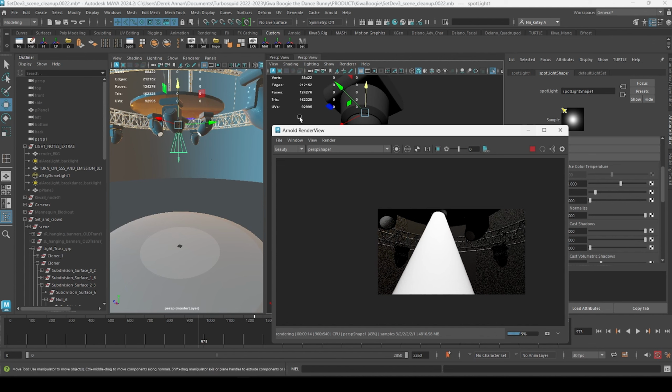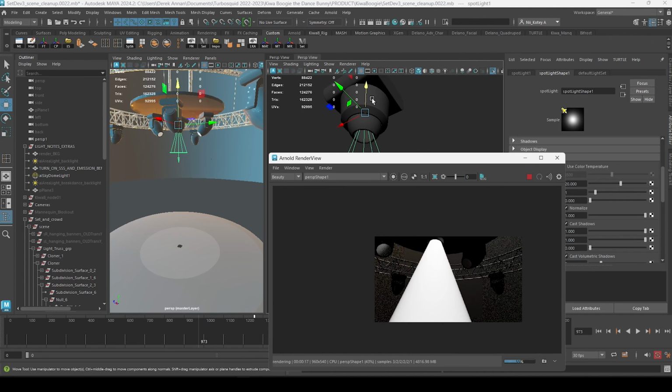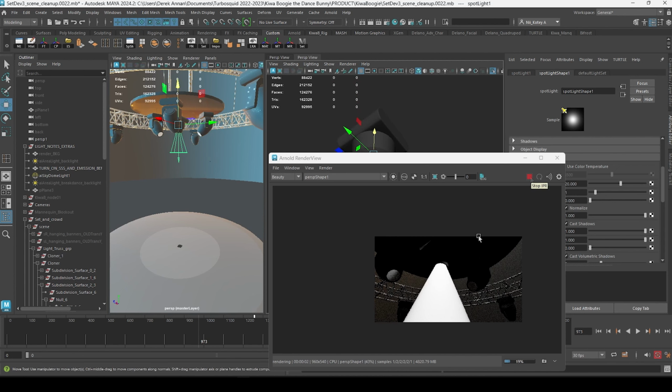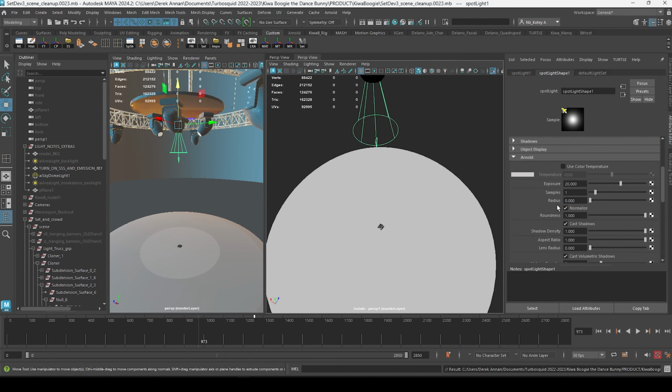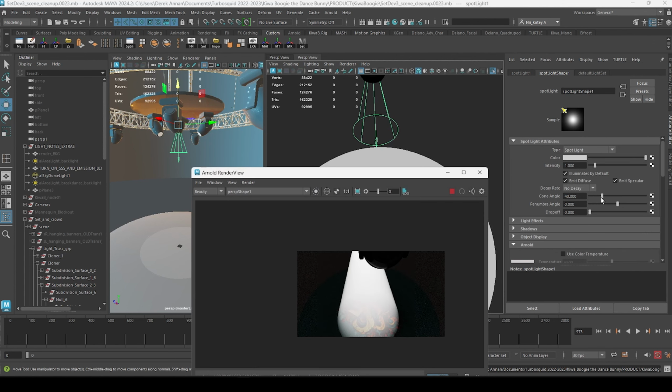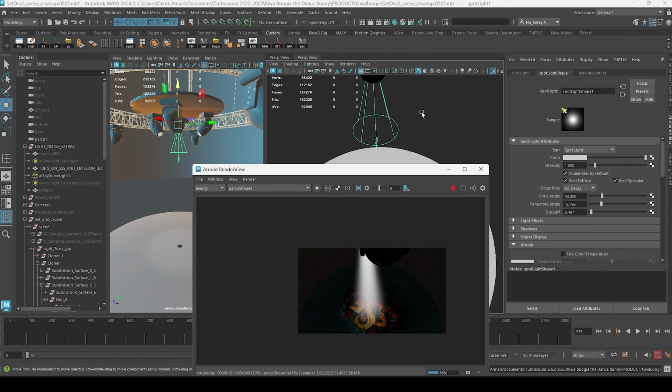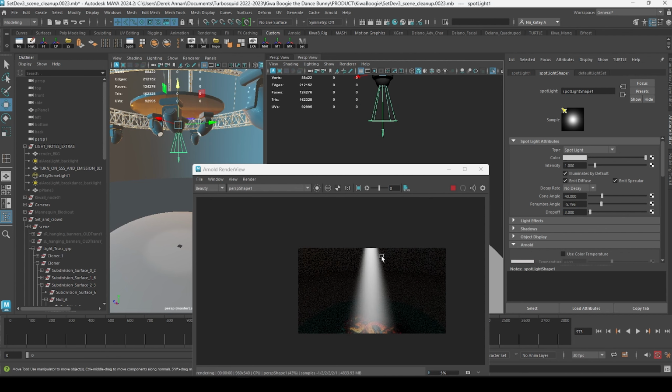Let me continue the processing of this light to turn it into a theatrical light, and I'll be able to analyze better. The next thing I'm going to do is soften its impact on the stage. So I'm going to grab the spotlight and crank down the penumbra angle. I'm going to set it to a negative value to really soften it. I'm going to crank up the drop off, not too high. Get a nice stream of light. I'm going to have to play with these parameters for the ones on the outskirt, so I don't go too far with that drop off. So something like that. All right, that should be good.